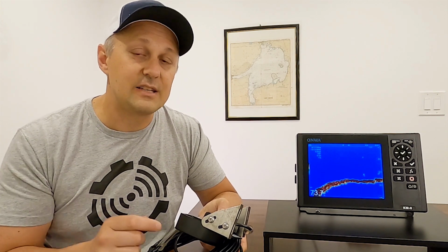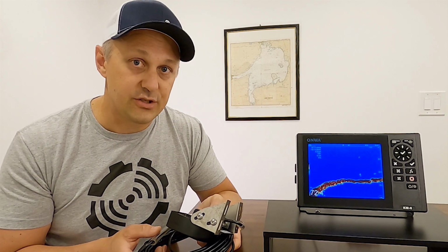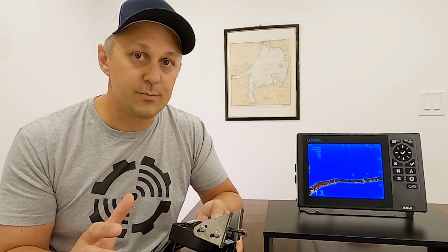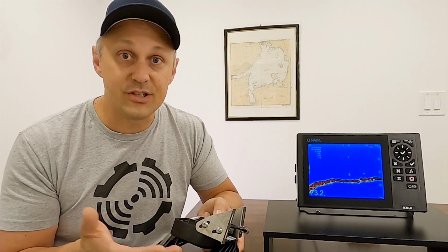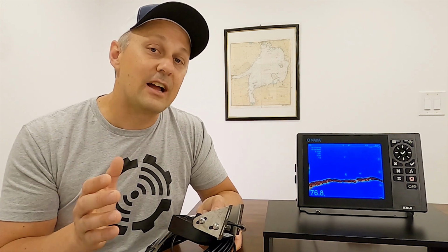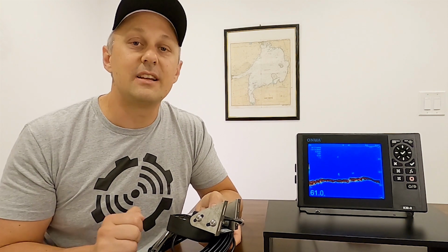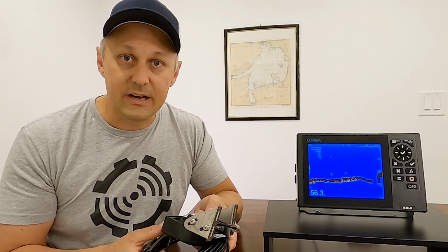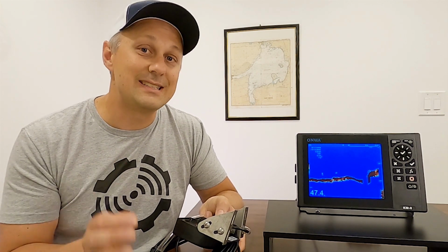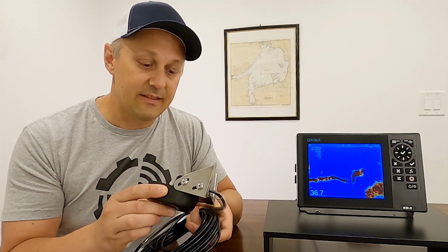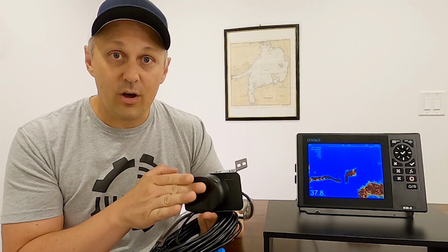If you have a fiberglass boat, then you can do an in-hull transducer where there's nothing you need to externally mount on the boat, so that means no holes below the waterline or nothing to damage if you hit an object. You can actually epoxy your transducer inside the hull. It will shoot the signal through the fiberglass and then allow you to get that depth and sonar reading. A lot of manufacturers make specific in-hull transducers. You can actually take a transom mount transducer like this one, especially one that has a flat bottom surface like this, and epoxy it directly in the hull.